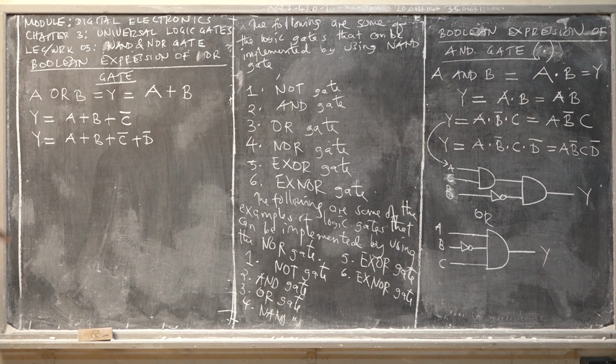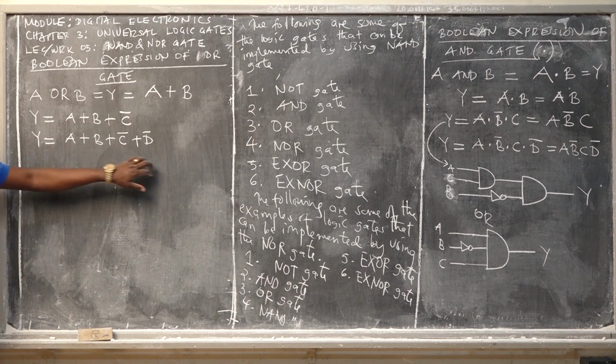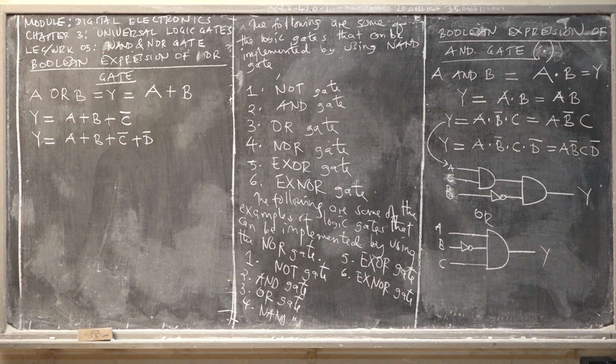First of all, if you want to know the number of OR gates, you first have to define whether you are going to use an OR gate of 2 inputs or 3 inputs. Right? For the 2 inputs, how many OR gates are we going to have? If you're using 2 input OR gates, how many OR gates are we going to have? 3. Others, no idea.